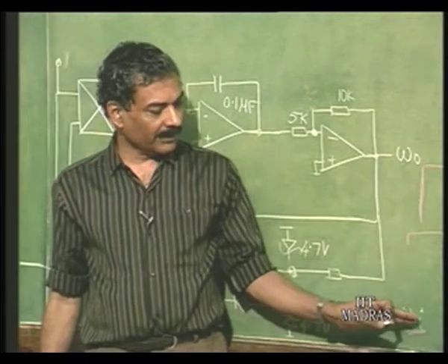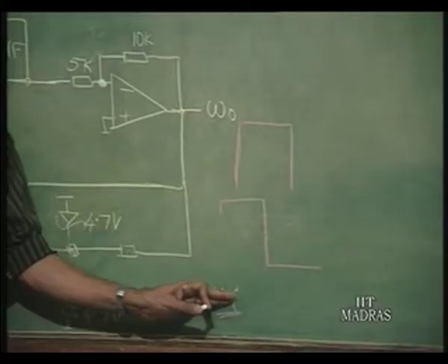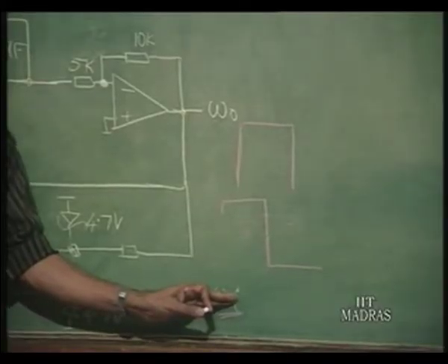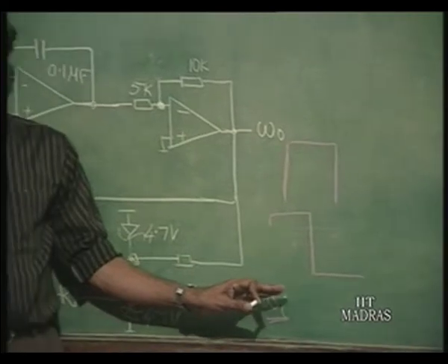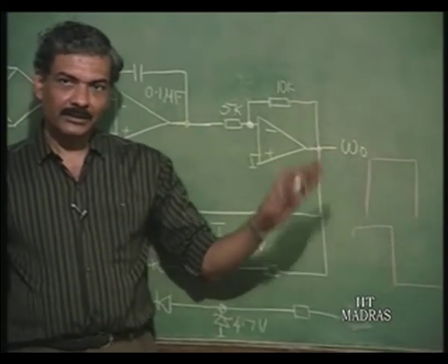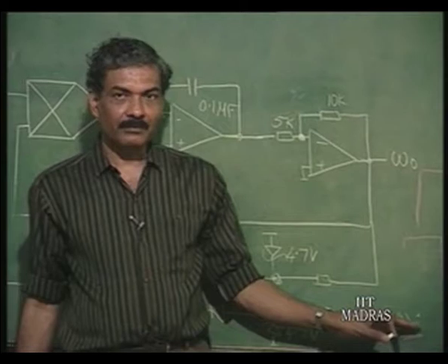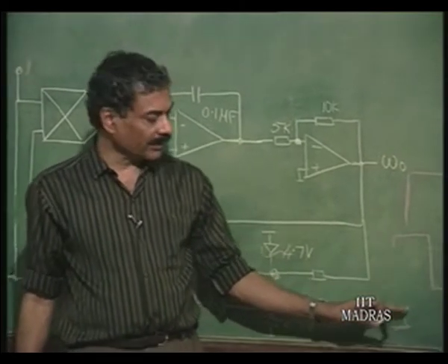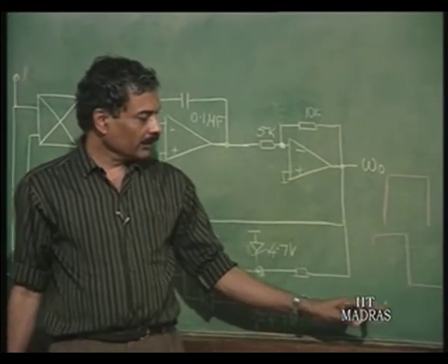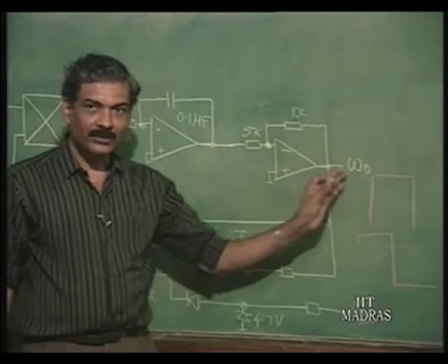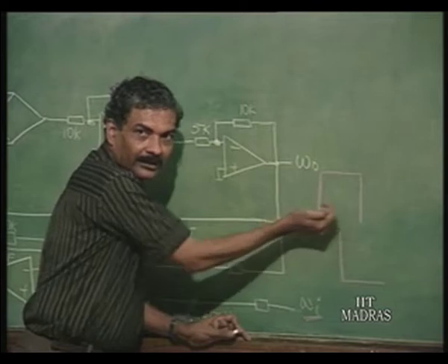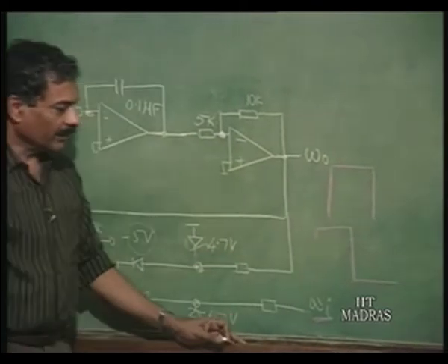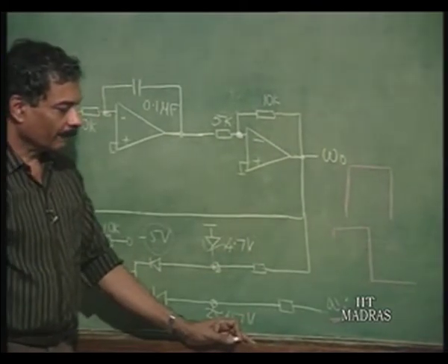Then we will make this vary automatically. That means we will apply an FM waveform here. Okay. So, around this carrier, which is close to free running frequency, we apply a modulating frequency to the carrier. So, we get an FM, okay, which is modulated by a sinusoid. Then you will see that this is also going to follow this in the same fashion. You can see the edge tracking, okay, and keeping itself under lock all the time.